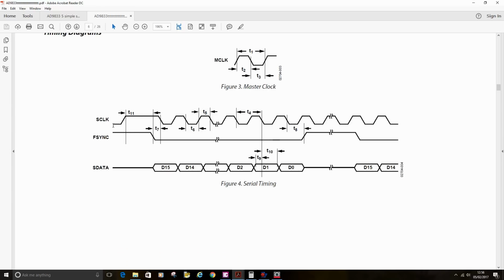There's our system clock. There's our frame select or chip select. It's active low, so we have to pull it down just like a TFT, run our 16 clocks, 16 bits of data, and then turn the chip select off again, and you see our data down there. So that's got to coincide with the data, and then obviously synchronize with the clock somehow.